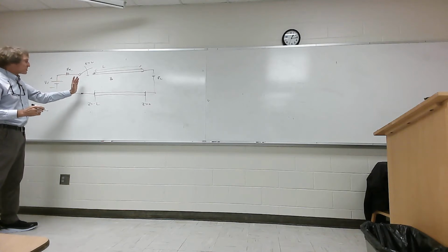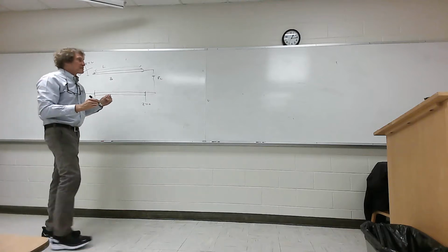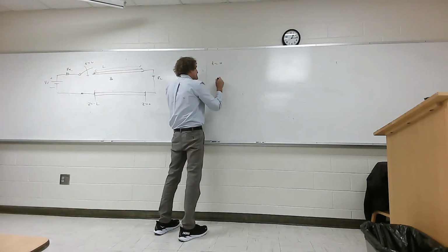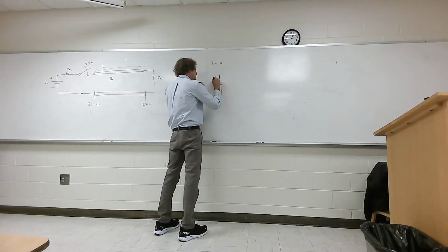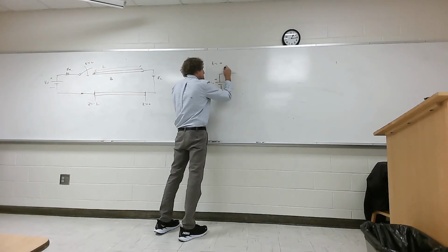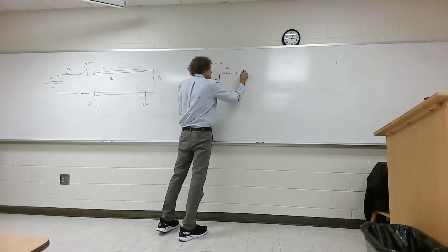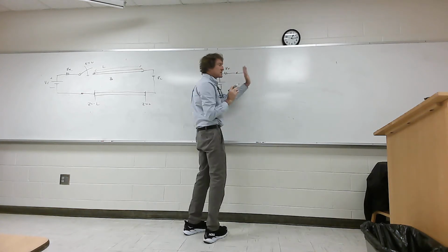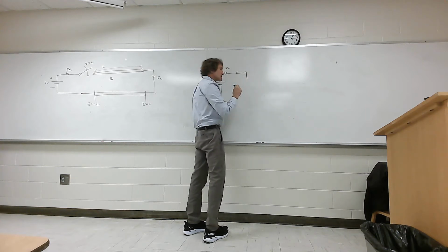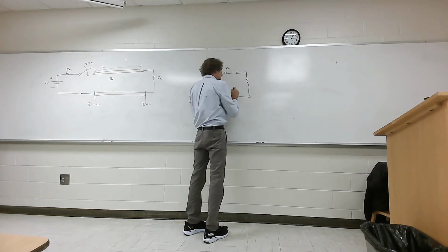So if I'm doing this problem right here, when you're at t equals 0, the circuit actually looks like this. I have plus or minus Vs, and I have some source resistance Rs, and just as that switch closes, it doesn't know how long the line is, so you can replace that entire line with just the characteristic impedance Z0.